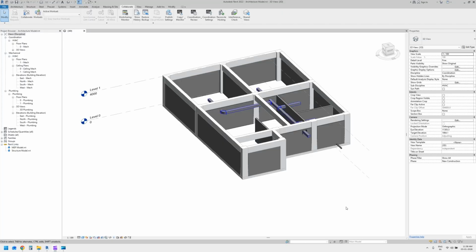Revit clash detection is useful for basic coordination. For advanced clash detection, you can use software like Navisworks, which is commonly used. So I have tried to give you real world knowledge, not just tool knowledge. This is how you can perform clash detection in Revit.